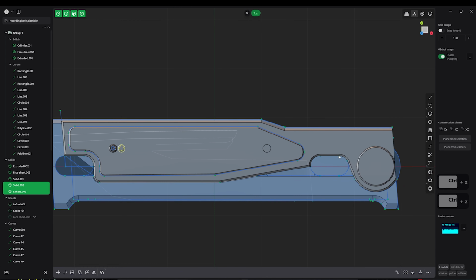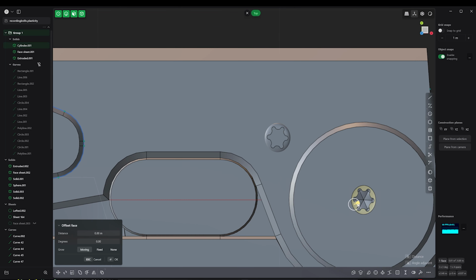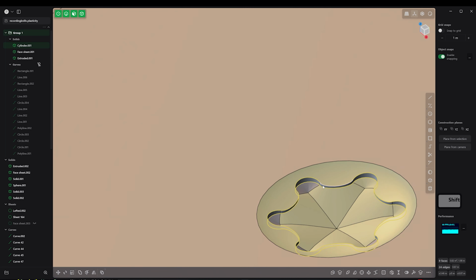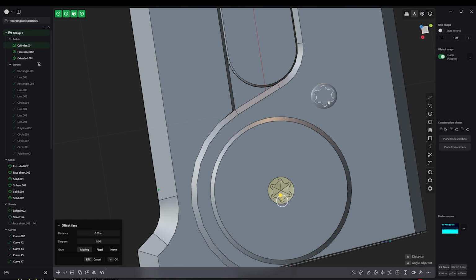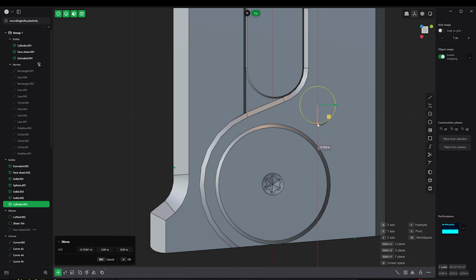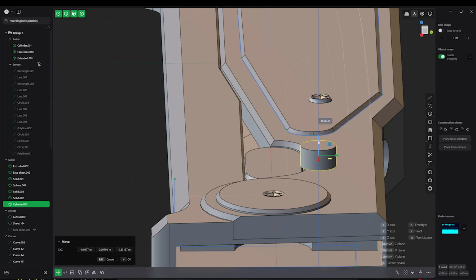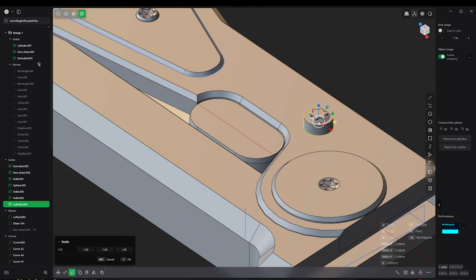I just duplicated the piece off. I would have skipped this part, but it actually shows an interesting piece of Plasticity, which is that I don't have to go in and recreate this piece. I can just select all the parts, and I could have done a faster selection job in that, and adjust the scale. And that's one of those elements of Plasticity that is truly very impressive.